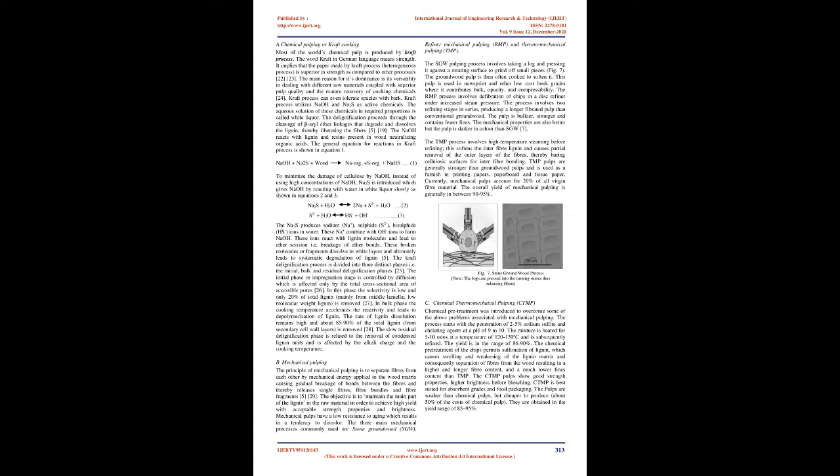The Kraft process utilizes NaOH and Na2S as active chemicals. The aqueous solution of these chemicals in required proportions is called white liquor. The delignification proceeds through the cleavage of β-aryl ether linkages that degrade and dissolve the lignin, thereby liberating the fibers. 19. The NaOH reacts with lignin and resins present in wood, neutralizing organic acids. The general equation for reactions in the Kraft process is shown in equation 1.